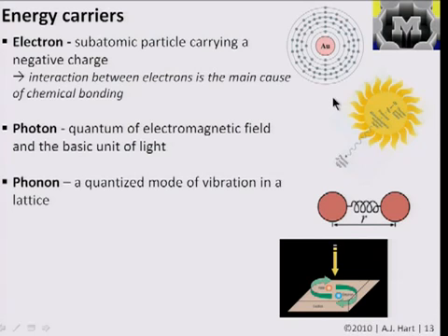So a beam that you might hit with a hammer will have a certain resonant frequency and therefore a mode of vibration. And likewise, the atoms inside a crystal will have many modes of vibration, except those frequencies of vibration will probably be a lot higher than the beam that will be vibrating at the macro scale. And we'll see this a lot in the case of thermal properties, because phonon transport is the primary means of heat conduction in insulating solids.